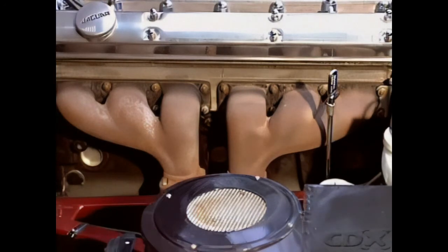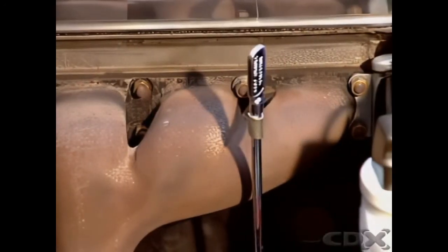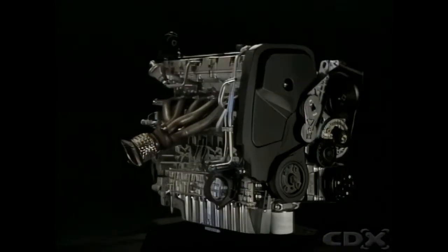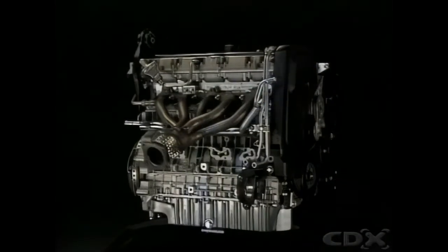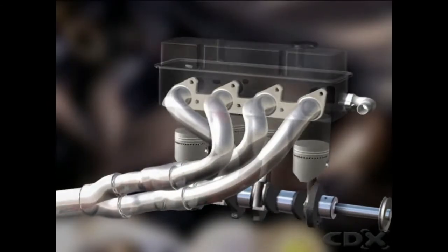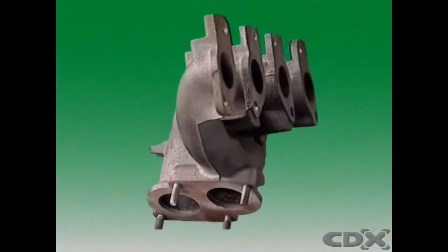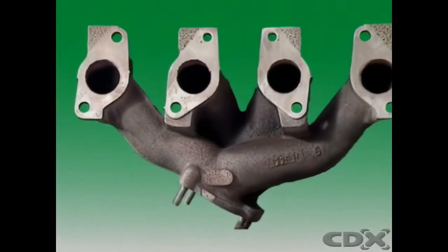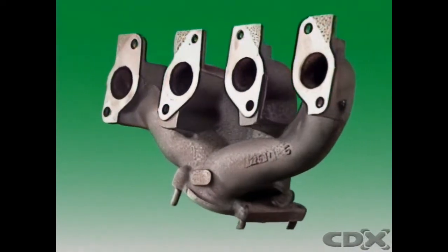The exhaust manifold is bolted to the cylinder head at the outlet of the exhaust ports. On passenger vehicles, the exhaust manifold is usually made of cast iron. Sometimes there is a separate passage for each exhaust port. The length of the passages in the exhaust manifold should be designed so that pulses of exhaust gases from one cylinder assist the flow of gases from another. It has large tubular sections to improve gas flow, and no sharp bends to slow the gases down.